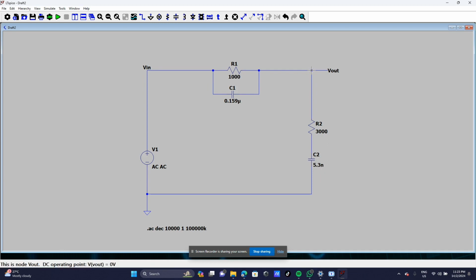And then we just assemble all of the circuit, put all the lines together, and then we're going to put the ground. Of course, every circuit needs the ground. And then we have V output and V input. Label V input on the left side, close to the voltage source, and then V output on the right side, right at the end of the line on resistor 1 and the parallel mini circuit.